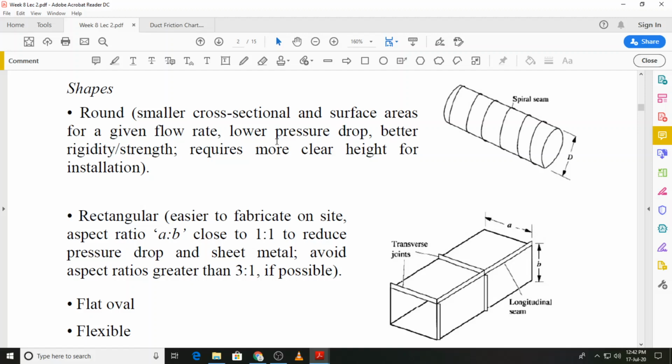When we say that in general round ducts are preferable to rectangular ducts, they have a smaller surface area, that also translates into less material cost. So they are going to be also less heavy, and we need hangers etc. to support the ducts, so we will require relatively hangers which are not that strong, in that sense that for rectangular duct we will need heavy hangers also.